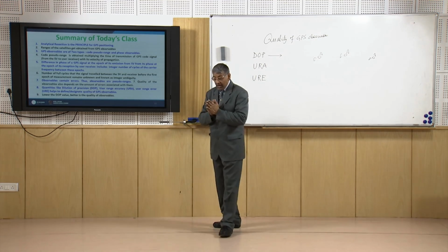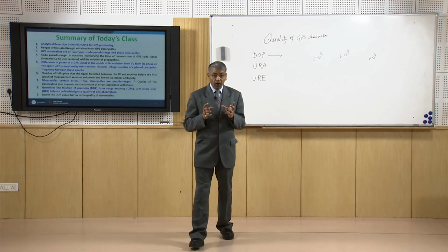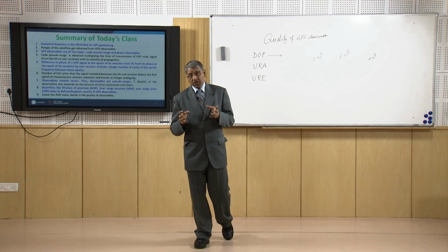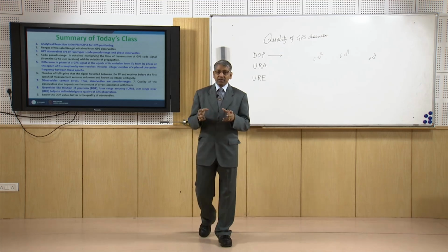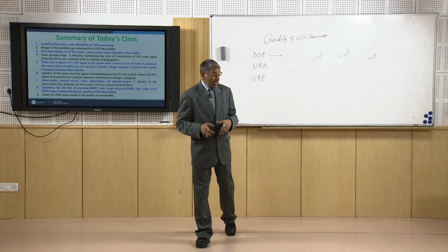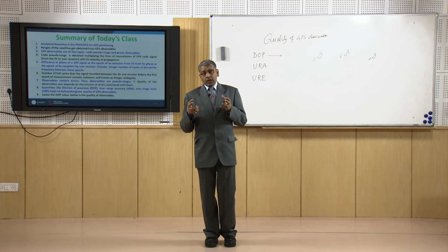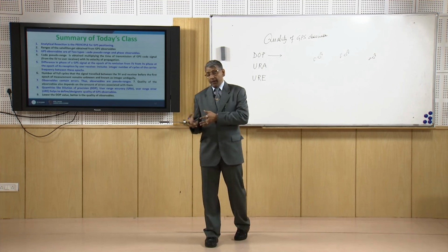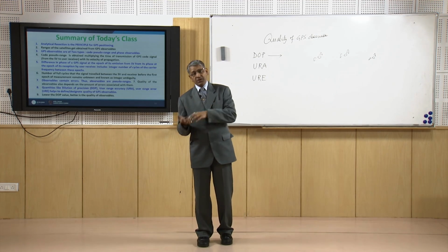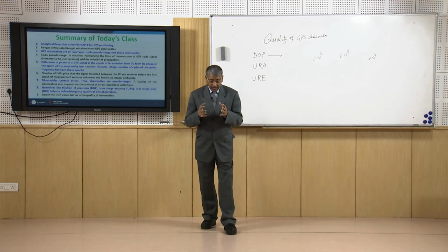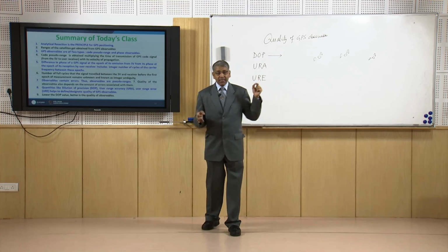We go for GPS surveying to find out the position of any point, and the position of a point using GPS is done by using the method of analytical resection. The method of analytical resection needs the known location of the satellites, which is available from GPS ephemeris data in the GPS observation, as well as the range, that means the distance between the satellite and the receiver.